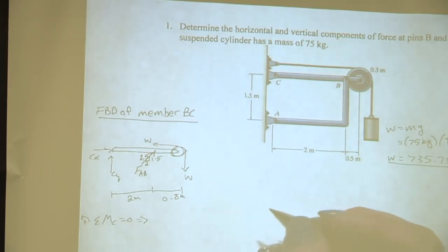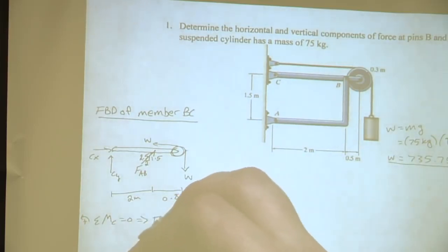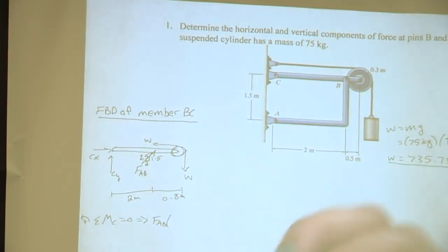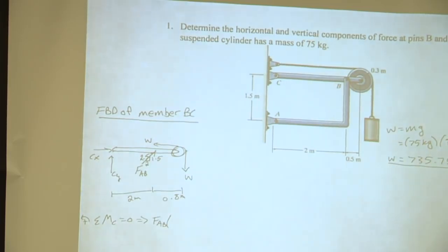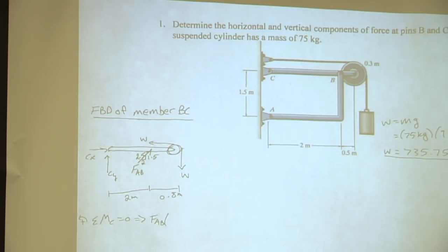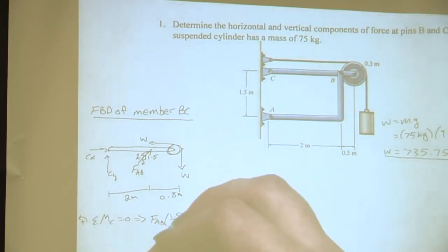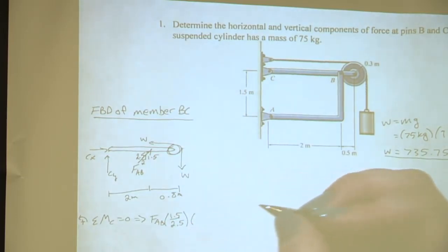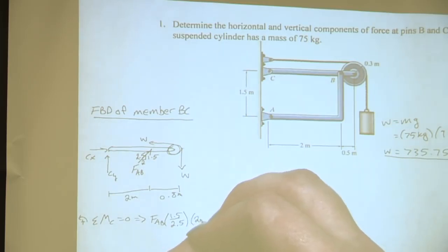would cancel out. Now what about the y component? Would that be positive or negative? Positive. Okay, awesome. How do you know it's positive? Because it agrees with our convention. Now for the y component, what do we need to do with that little triangle? It's going to be a ratio, so it's going to be 1.5 over 2.5. Does everyone agree with that? I'm gonna go with yes. Okay, and then we need to multiply it by its perpendicular distance, which is 2 meters.